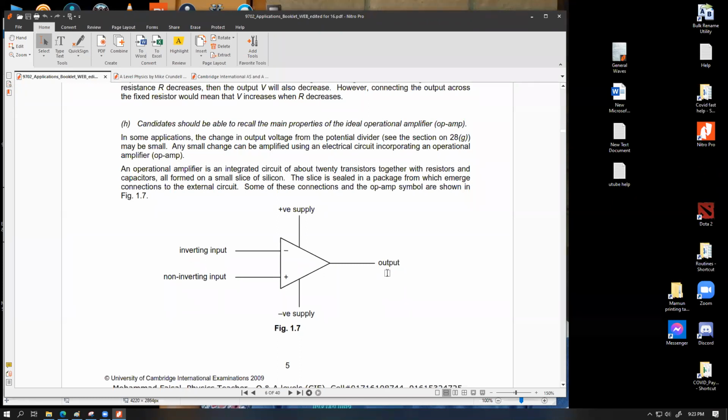So you are increasing joule per coulomb. You're inputting 0.1 joule per coulomb, but you want an output of 2 joule per coulomb. So you have to increase the amount of energy by 20 times. But energy cannot be created or destroyed. It can only be transferred from one form to another, from one place to another place. Which means if this device has to work as an amplifier, if this device has to increase the voltage of an input signal, it has to be fed some energy. That feeding of the energy is where the supplies come from.